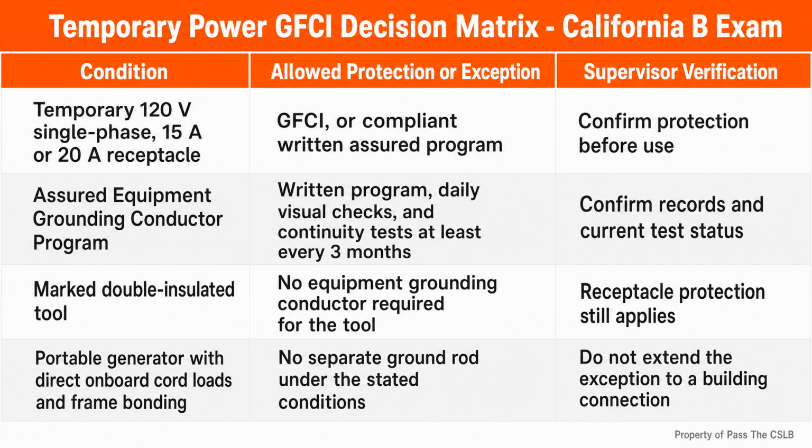Downstream plumbing can change. A later repair can replace part of a metal run with cross-linked polyethylene or another non-conductive material. A grounding interconnection placed deep inside the building can then be separated from the metal pipe that reaches the earth. Keeping the interconnection within the first 5 feet of entrance limits exposure to those downstream alterations.